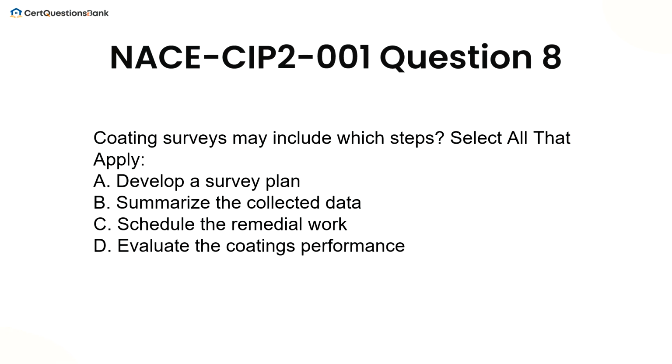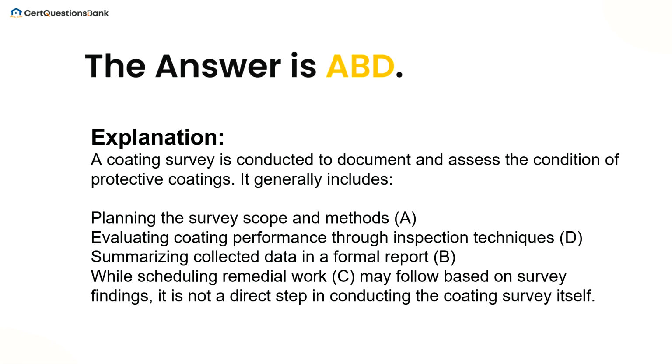Coating surveys may include which steps? Select all that apply. A. Develop a survey plan. B. Summarize the collected data. C. Schedule the remedial work. D. Evaluate the coating's performance. The answer is ABD.